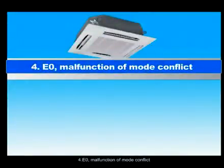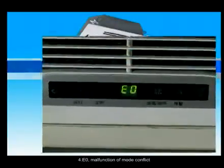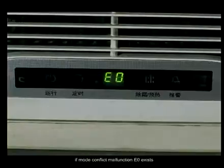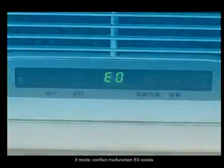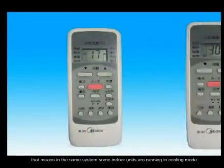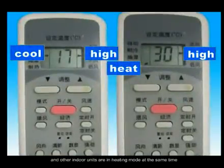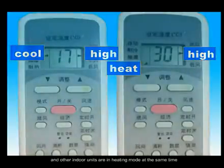4. E0 malfunction of mode conflict. Repair instructions when E0 appears. If mode conflict malfunction E0 exists, that means in the same system some indoor units are running in cooling mode and other indoor units are in heating mode at the same time.